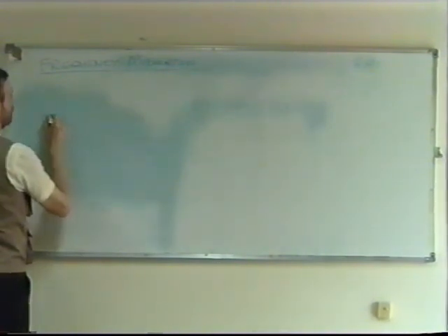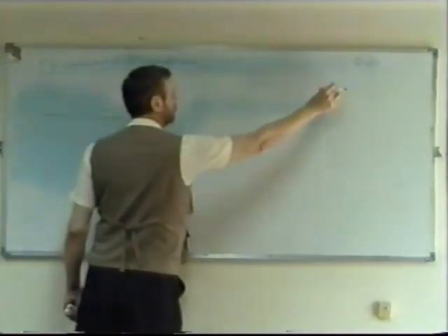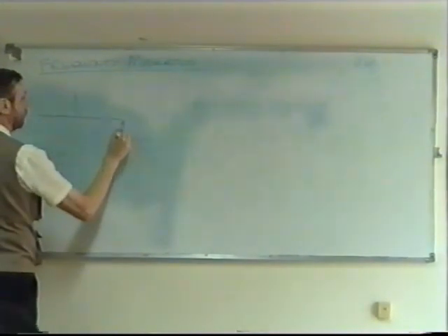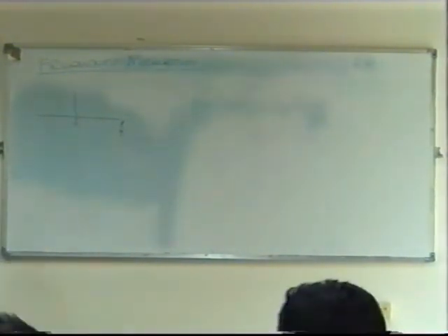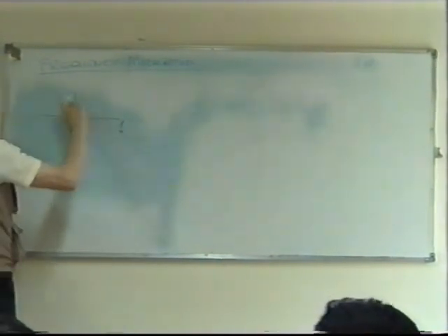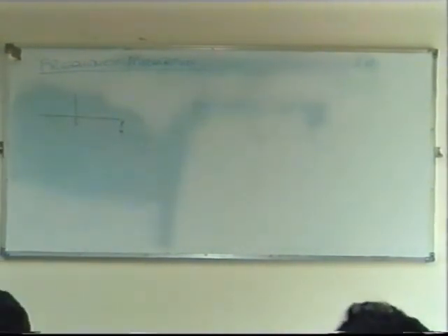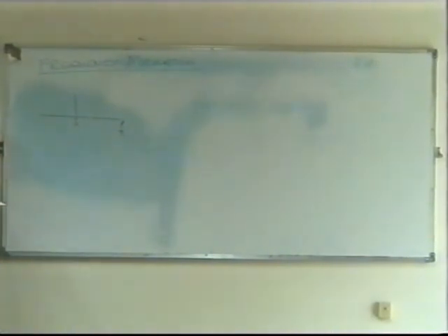The easiest way to show frequency modulation is not to choose a waveform like that, it's a little bit complicated. It's to choose a spectrum here, where this is our carrier. Now, if I was to amplitude modulate that carrier, I produce two sidebands, don't I? Well, what we do with frequency modulation, I cause the carrier to increase and decrease in its frequency according to the amplitude of our modulating signal.